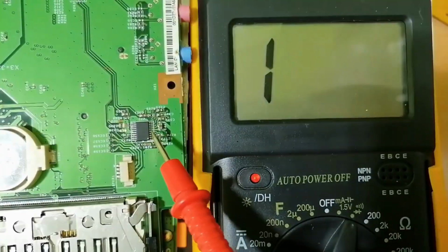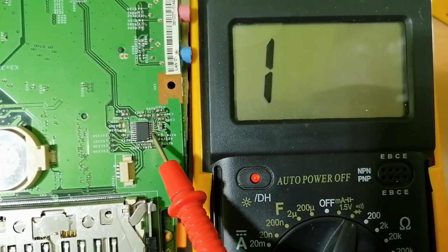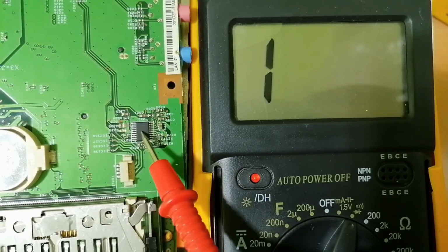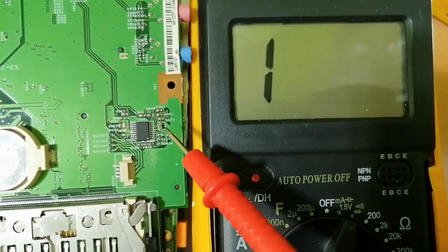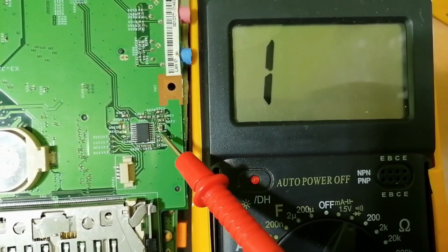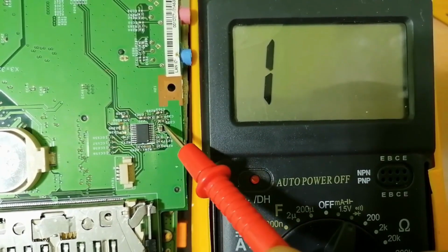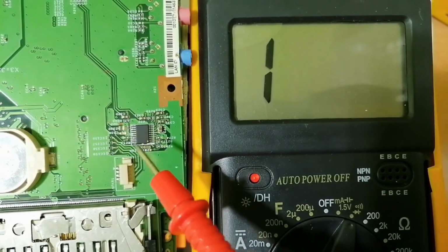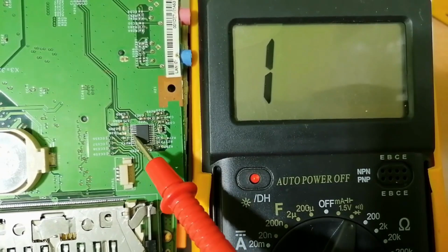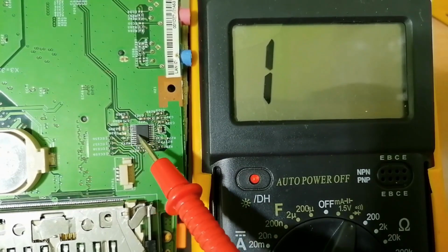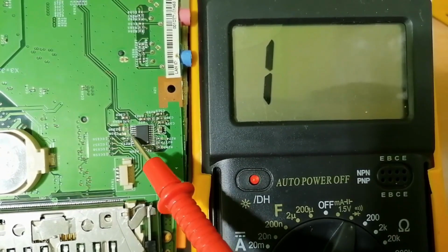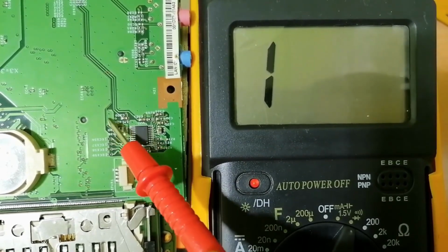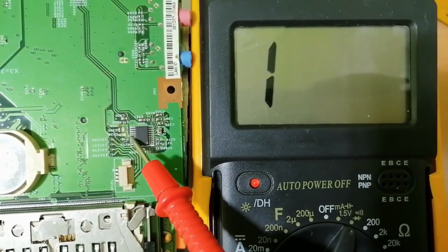Okay, so this information right now we will use to find a short circuit. Because the ceramic capacitors are connected to the IC on one side and to the ground on the other side, and of course the IC itself is connected to the ground, as you can see, in one or two of its pins. Do you see here? These two pins basically are connected to the ground, as you can see. Why? Because we have this bolded path here, meaning this is the ground.